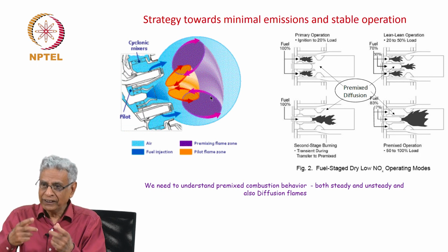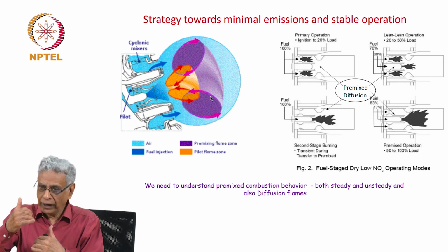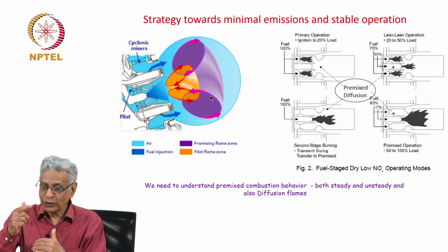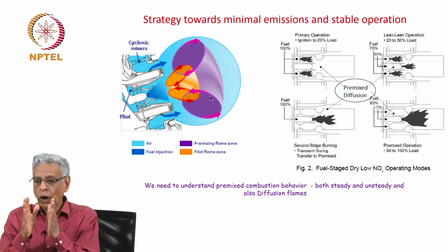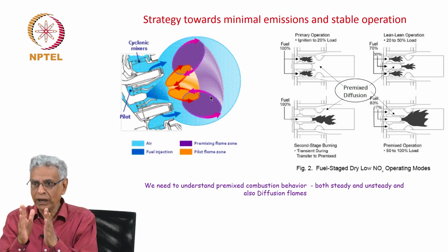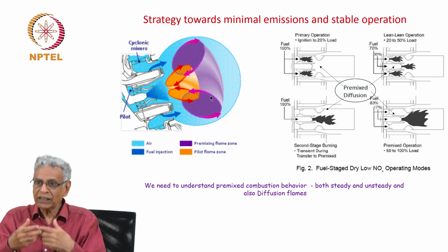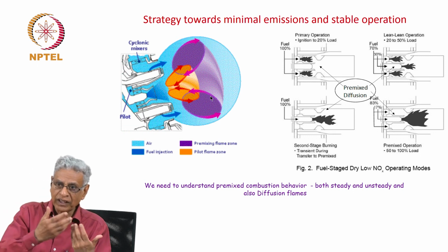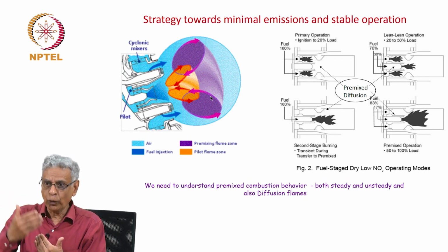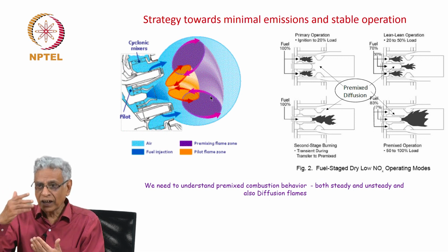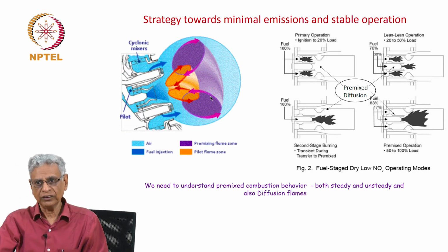Now, this so called quench means you give a little more air, do not let the temperature rise, but temperature is limited. Now, you allow the residence time in this domain to be small. So, the reaction occurs, completion of oxidation reactions occur such that the NOx does not necessarily go. So, it is called rich quench approach to the process of NOx reduction.